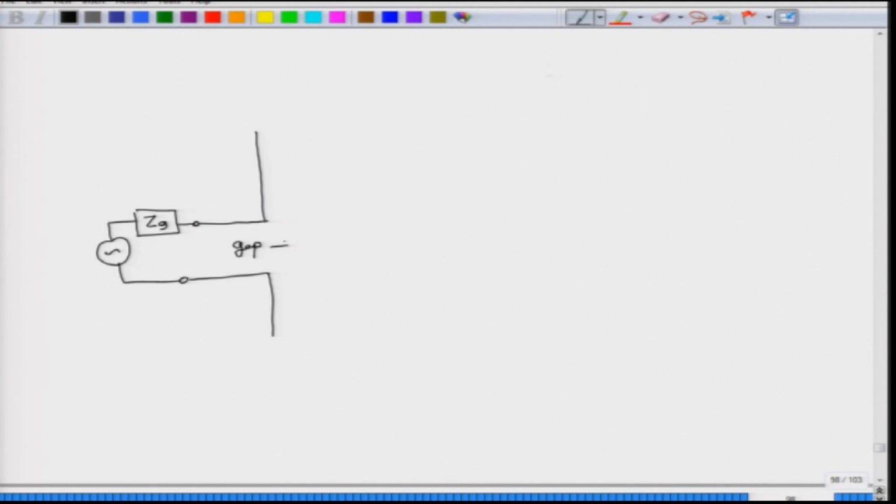And we will put some length here. If you consider this as the z equal to 0 point, then the top portion will be z equal to plus L, and this one would be z equal to minus L. This is the antenna part, this is the transmission line feed to the antenna, and this of course is the voltage generator that will be generating whatever power is necessary to feed the antenna. Of course, information will be residing in this voltage and it would be time varying, so the current on the antenna terminals will be dependent on what voltage and transmission line feed we are using.